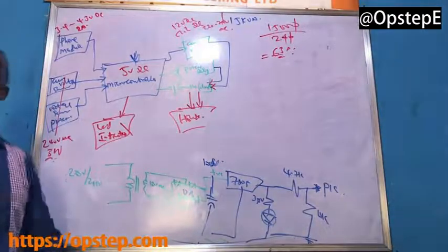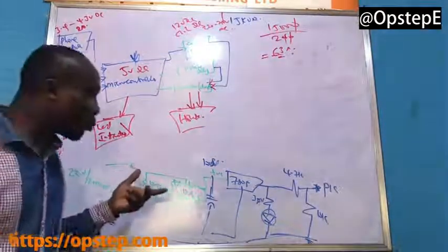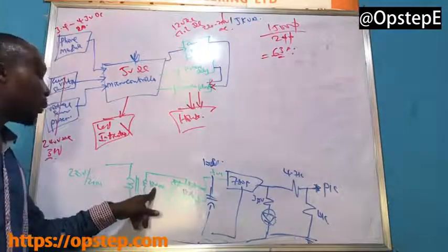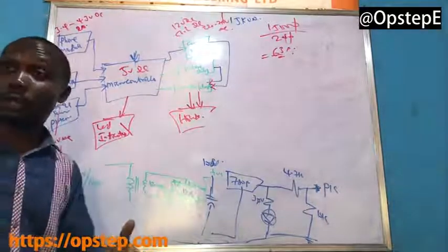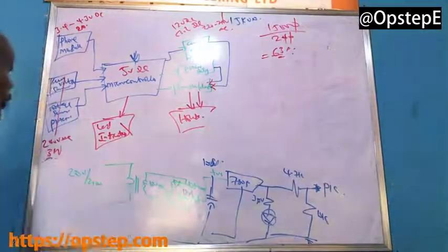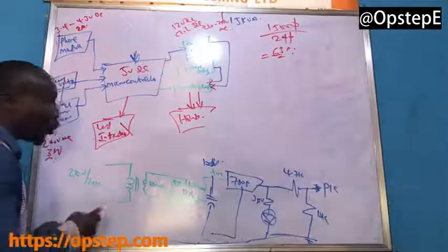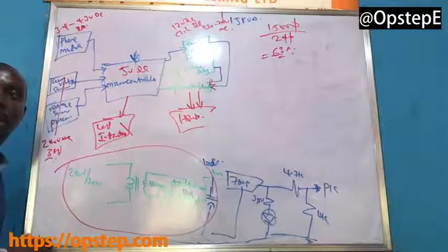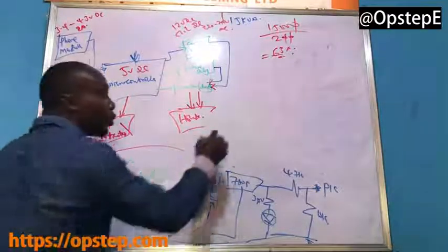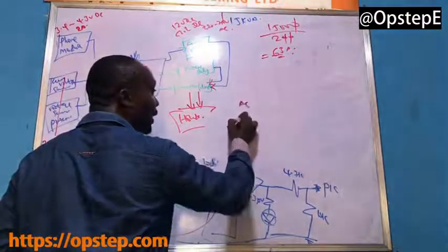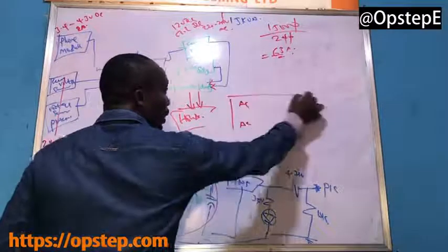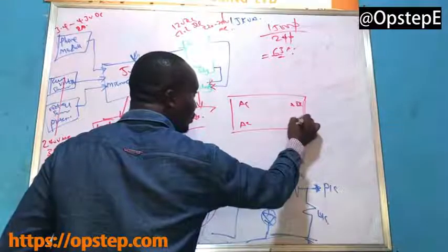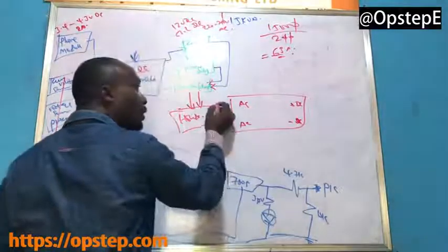Generator. But let me say this. In the process of designing the system, we did not use a transformer. What we did is that we got a solid state transformer, or a voltage module, that already helps us. The voltage module already has all of these inside. Are you following me? So what we simply did was we fed AC into it. It has an AC point, and it has a DC positive point and a DC negative point.